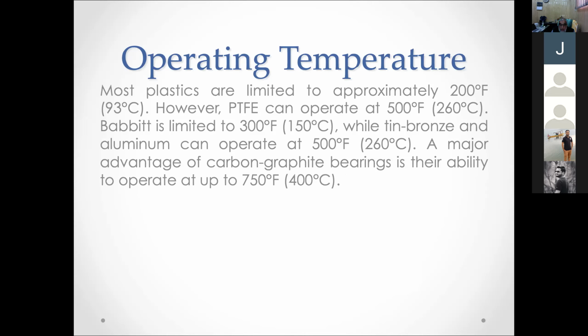Remember this. Whenever you will get some P value and the temperature is high, you can use carbon graphite. But the graphite alloy bearings are typical bearings. They are not commonly available.